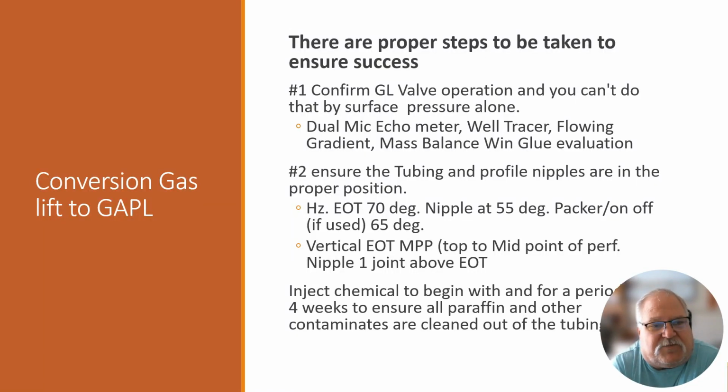So, some proper steps to be taken to ensure success. Confirm the gas lift valve operation is working, and I can't stress this enough: you can't do it by just looking at pressures. It means nothing at surface. You have to either go in with a gradient, do a flowing gradient, to make sure they're all good. Maybe a dual mic echo meter might show that things are good. Probably not, but it's one of the things we do.